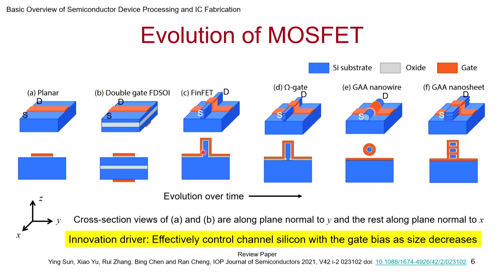So now this is good, but again, people asked, what about the bottom? If you can get better control of the volume if you can also encroach on the bottom side, which is actually electrostatically connected to the body of the transistor, right? You can bias it with the well and all that, but still that is a challenge. So then they went for the omega gate. So essentially you do some undercutting, and it looks like the Greek capital letter omega. So you have more than 3 sides of control.